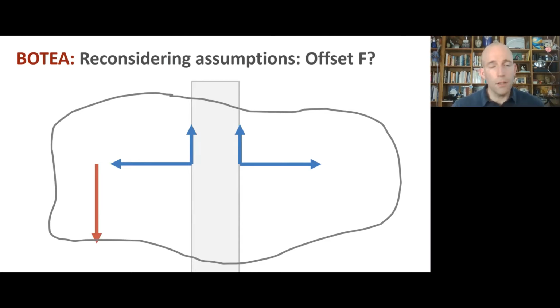Well, the force balance in the vertical direction would still work out the same, and in the horizontal direction. But we could probably see pretty quickly that our moment balance is going to fail. If we pick, say, this point in the middle, all the blue forces are going to sum to 0 moment, but this payload force is going to make the thing want to rotate counterclockwise.